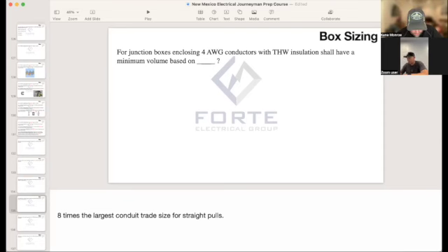Oh, so that's what the amperage is. Exactly. And you have 15 amp circuits, so you need to divide again, 69 divided by 15. 4.6. Exactly, which rounds up to 5. Okay, that makes sense now.